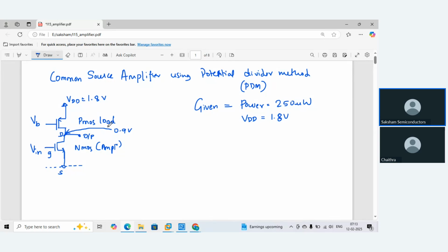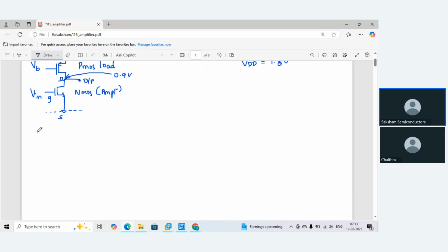Now here I don't know the sizings of the MOSFET, so basically I don't know the W and L ratios of the MOSFET. Those are the very important things to figure out, W and L. So for that, as the first step, I'll choose L equal to 4 times the technology node.